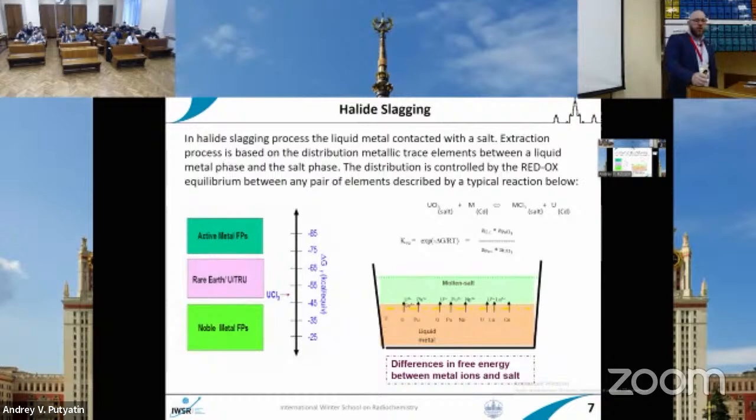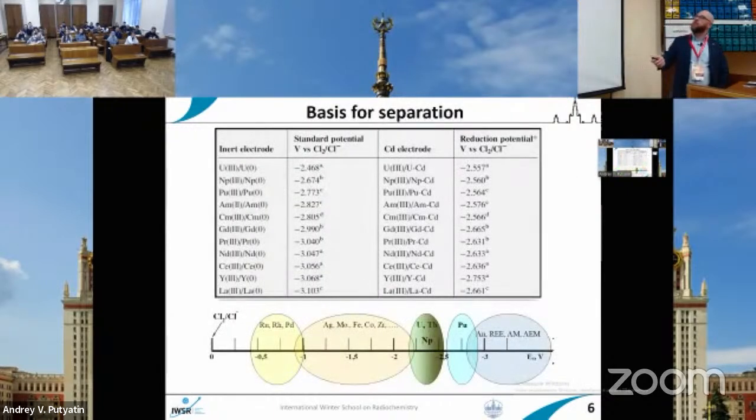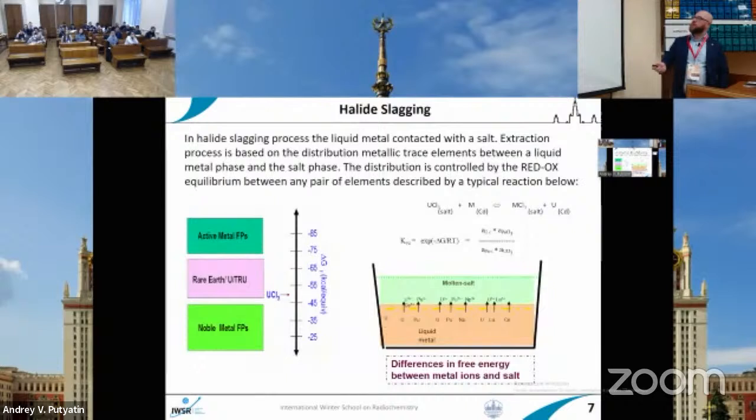So, how to make this formation of the metals? There are different ways. One way to separate metals from each other is the use of, let's say, solvent extraction, not solvent extraction exactly, but in an electrochemical fashion. Here there is a liquid metal cathode and the molten salt, so there are two liquids.